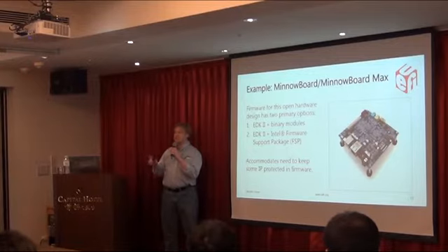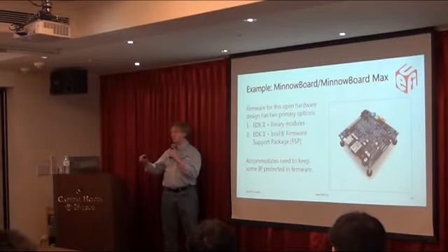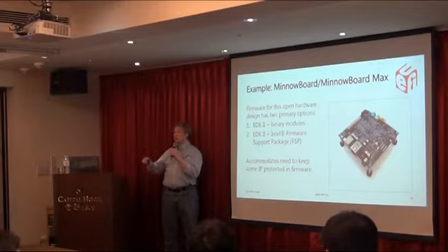Now, for most people, that's not a problem in open development, because you're talking about things that are fixed on the board. So we'll take the Intel Minnow board as an example, because it's one of the boards I know. That actually is EDK2 plus binary components for memory initialization and some of the CPU initialization. So the memory initialization, all the memory on the Minnow board is soldered to the board.